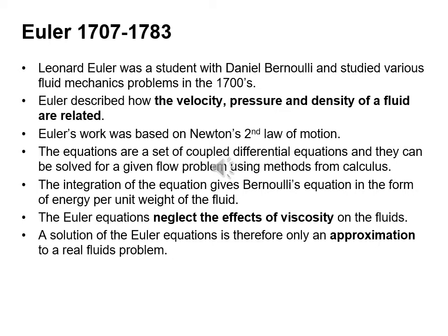So Euler was a student with Daniel Bernoulli and studied various fluid mechanics problems in the 1700s. He described how the velocity, pressure and density of a fluid are related. His work was based on Newton's second law of motion. The equations are a set of coupled differential equations, and they can be solved for a given flow problem using methods from calculus. The integration of the equation gives Bernoulli's equation in the form of energy per unit weight of the fluid. The Euler equations neglect the effects of viscosity on the fluids. A solution of the Euler equation is therefore only an approximation to a real fluids problem.